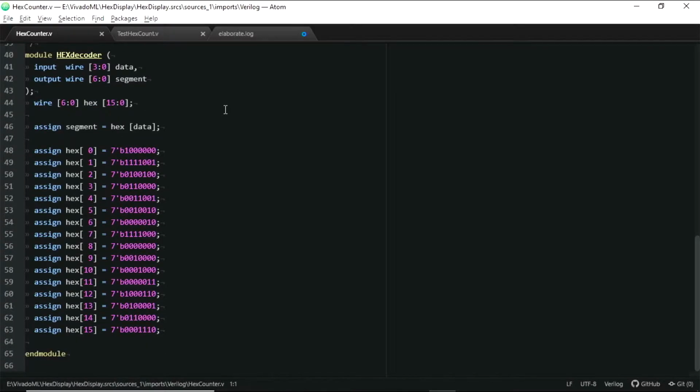And this is for displaying hex codes on a 7-segment display. And it's got some more problems with it, but we're not going to discuss that right now. But see if you can find where the problem is here. It's in these bits. It's hidden in here somewhere. And it's common anode, so the zeros are actually on and the ones are actually off.